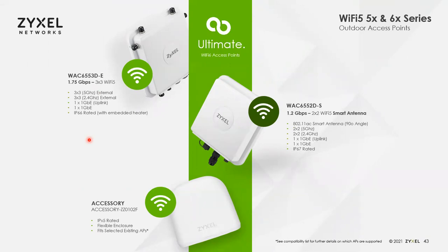And it has external antennas that are optional. We sell an ANT 2105 antenna that you screw into these, or you can source your own specialty antenna based on what you're trying to do. So you can get directional antennas for one radio or whatever for doing point to point, if you're trying to do backhaul. It's IP66 rated.